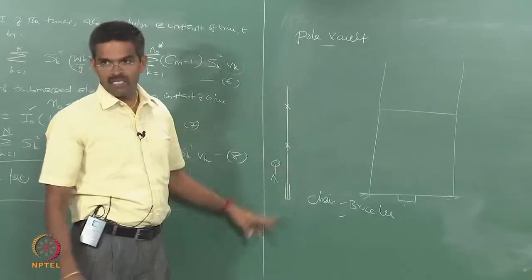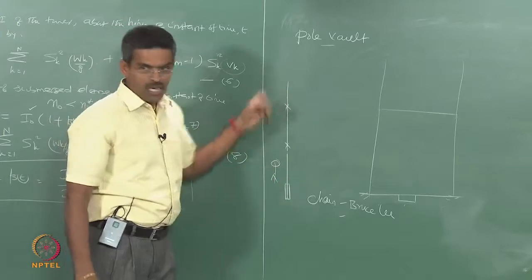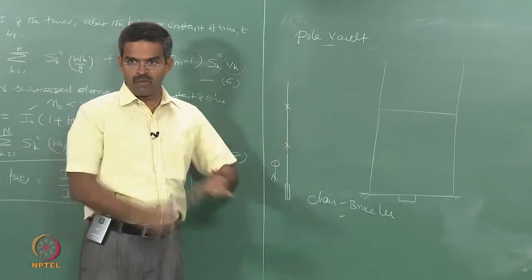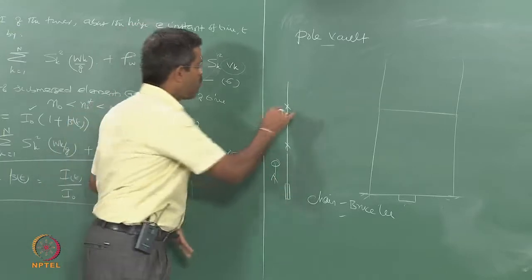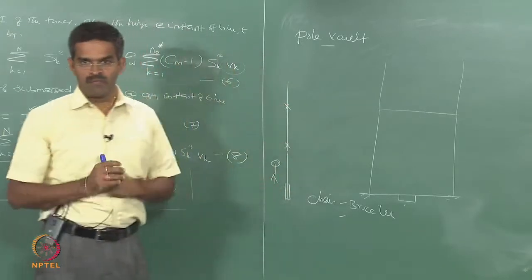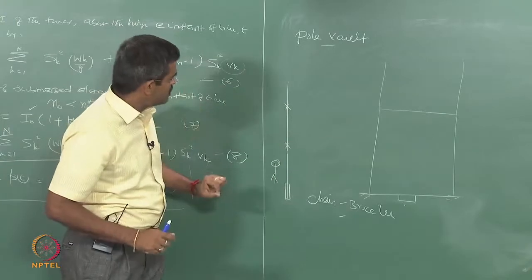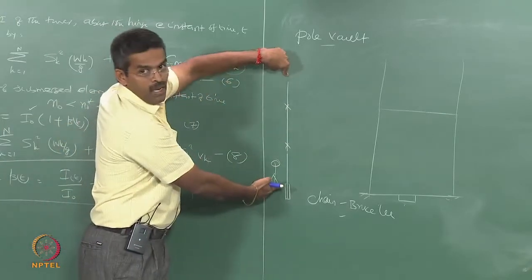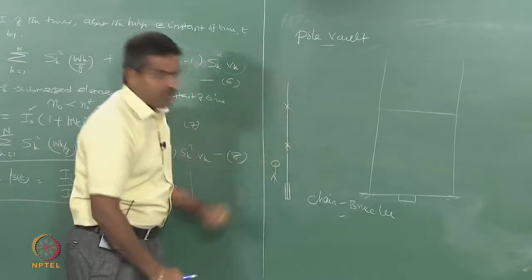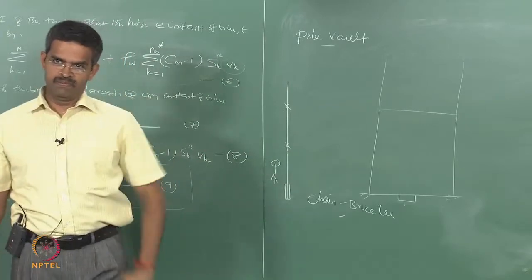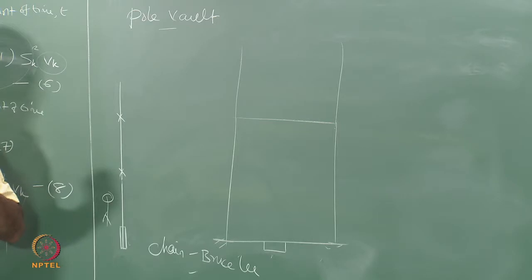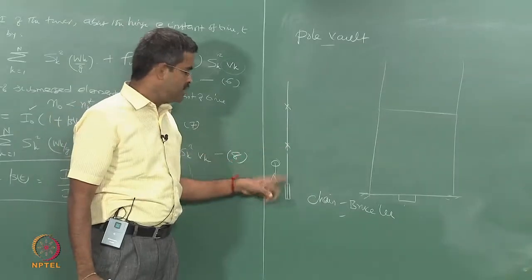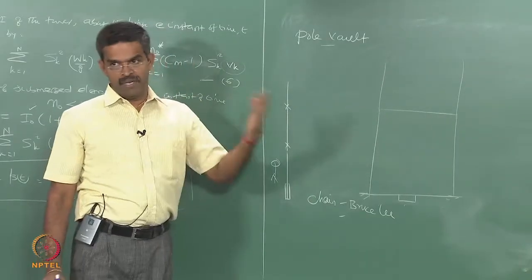The moment you have multi hinges, you can make the chain straight, you can disconnect the chain to not become straight, can become segmental also. Okay. Now the moments at these points in design perspective will become 0. So you can devise or design the system not as a single member but as pieces of members, therefore the section dimensions will become very small for the same load applied on the system. Okay. So multi hinges will have advantages and demerits.